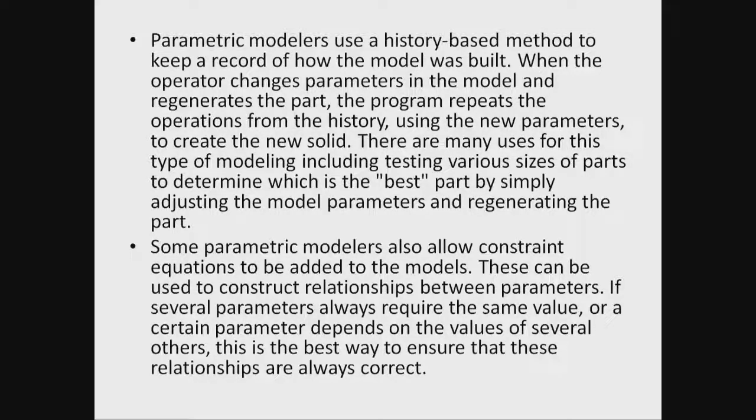In our case of electronics, I will say I have started with locating a connector on one side of an enclosure, and then I have put a printed circuit board which comes near it. Now you see there is a chance of something attaching with each other. If there is a way to tie these things up, I can avoid unintended interference within these objects. So, all I need to do is lower or raise the PCB height. Similarly, I can change the connector position,